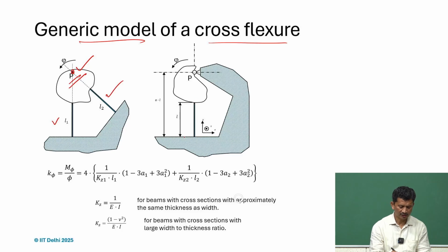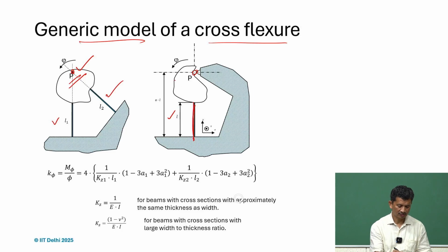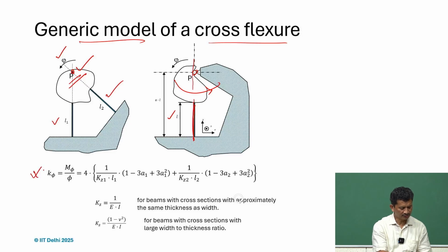Similarly, we can have just one leaf spring over length, pivoted at P. We can write the equation, so this can also bend like this. Here, if we apply a moment, there will be angular deflections, and from the overall stiffness we can get rotational stiffnesses.